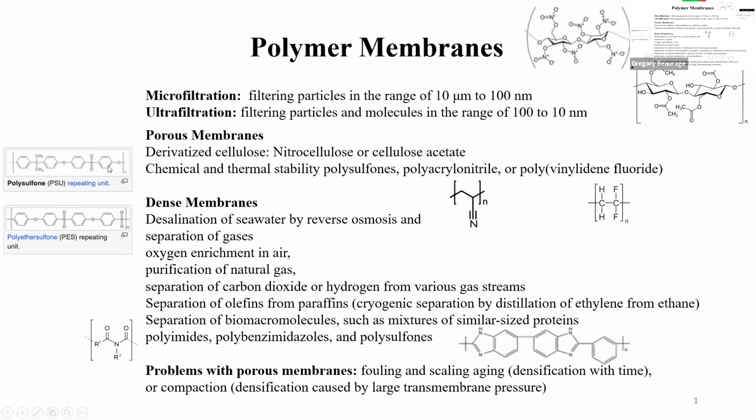So you want high modulus in this. You want good tear strength. So you're going to find all the high strength polymers used in this, like cellulose, a relatively strong polymer, and then cellulose nitrate and cellulose acetate are the two osmosis membrane materials.